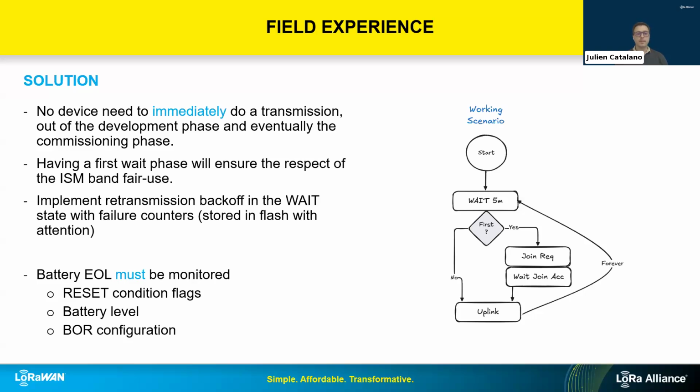And a side comment related to that, because it's also a problem I see basically on a weekly basis on the fleet I manage: users declaring their device as a 104 device, but in fact they are 102. So the LNS is expecting incremental DevNonce, but the device is sending random DevNonce. If the device sends DevNonce 1, okay, it joins. The next time it sends a random value, like 1000, it joins. But the next time it generates something like 200, and the LNS says, oh, in 104, I cannot get 200 after 1000.